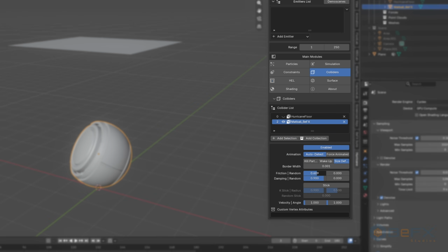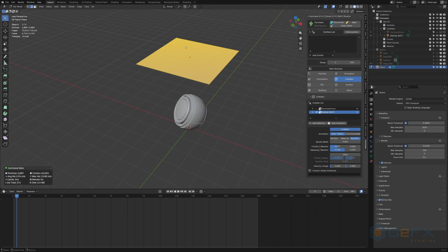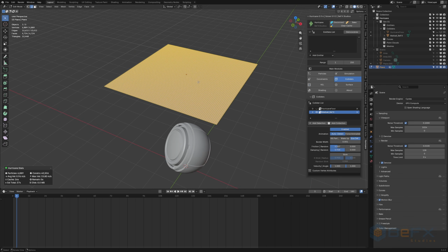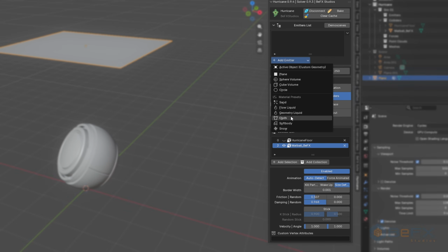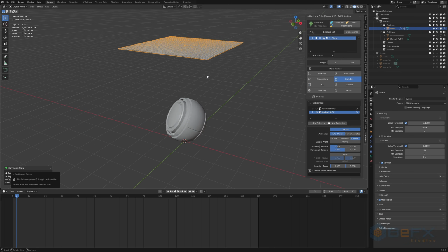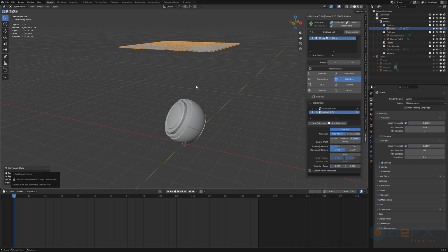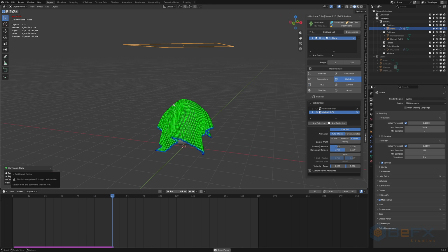Before assigning the emitter, it is essential to ensure that our mesh has good geometric resolution or subdivision count, as this will determine the level of detail and folds with which the cloth can wrinkle. Once the resolution is verified, we select the plane, assign it as an emitter, and choose the cloth preset. As always, Hurricane will automatically configure the solver with optimal settings for cloth simulation. Next, we play the simulation and we can already observe a highly satisfactory initial result.